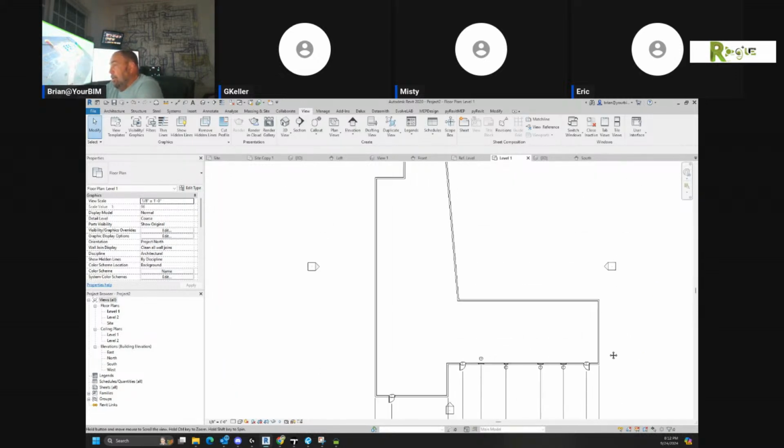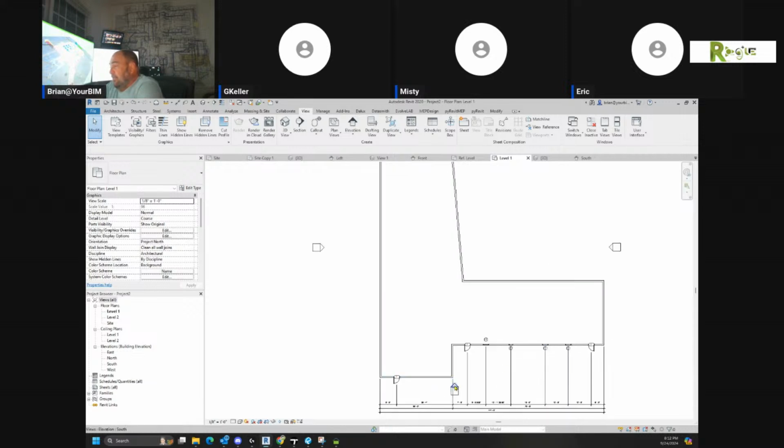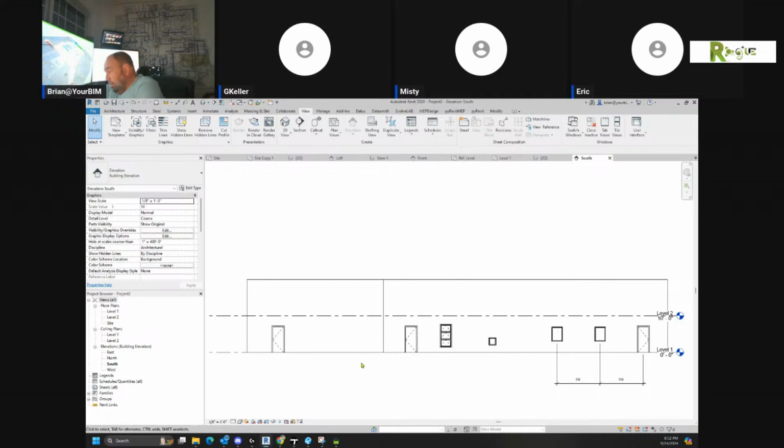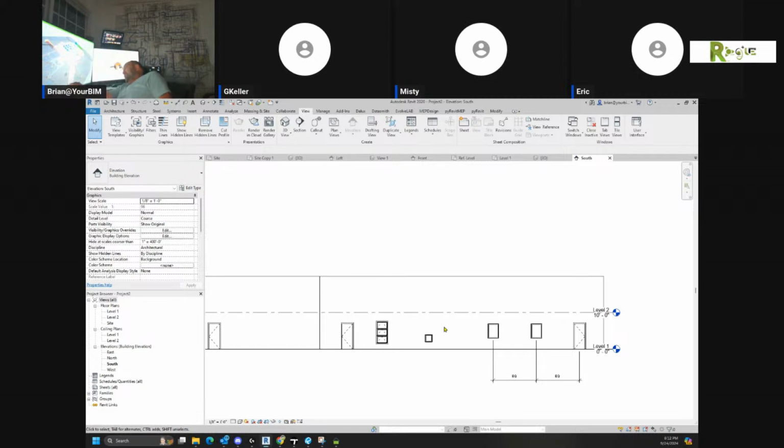Another thing you should be putting on a sheet of paper should be these elevations. See that elevation right there? That should end up on a piece of paper. And typically it only is going to have a couple notes on it. It's going to probably say, this thing's got brick on the outside, and it's got aluminum downspouts, and it's got vinyl soffits, and it's got asphalt shingles. And that's typically what an elevation is in a set of architectural prints. Okay. And I want you to try to make the drawing, so then we can try to teach you how to make the drawing better. That makes sense?